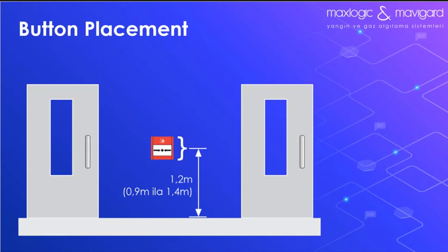After the standard has been updated, information on the criteria for projecting the alarm buttons has been given in the 6.5.4 alarm buttons article of the standard. 6.5.4 Alarm buttons should be placed on escape routes, at all doors opening to the inside and outside of escape stairs, and at all exits to the open air. They can also be placed near special hazards and firefighting equipment.